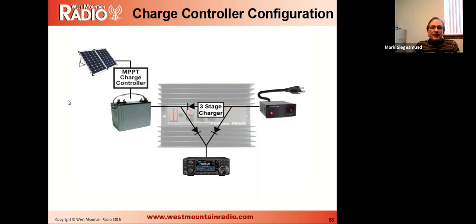With the PG40S that we were talking about earlier, you can connect a solar panel to a charge controller to the battery, and that can be in parallel with the PG40S. In general, it's okay to connect battery chargers in parallel.